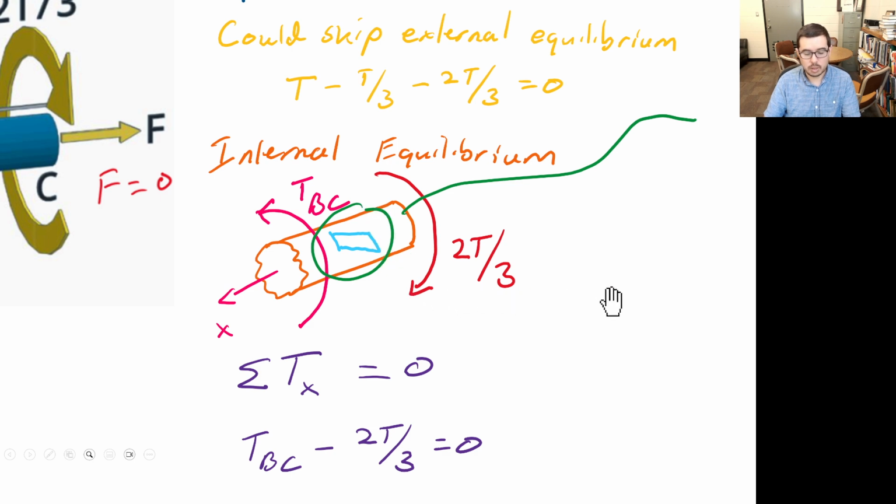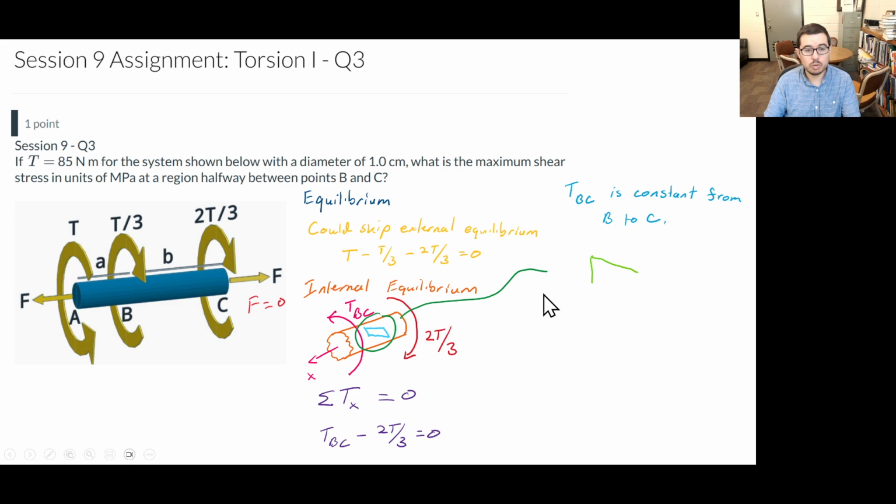When we zoom in or draw this element, we can say X is coming out the left side here, on this face, and we have this tilted element now. What's causing that tilt? Well, shear stresses. This side is being sheared in that direction, and this side is being pulled right in that direction, and that shear stress is causing this.